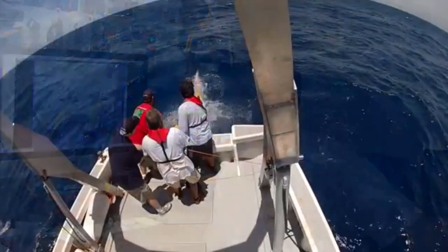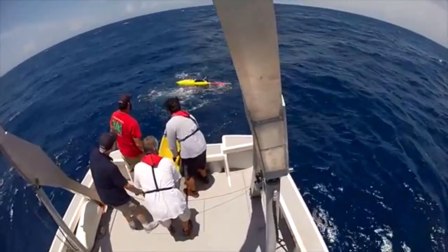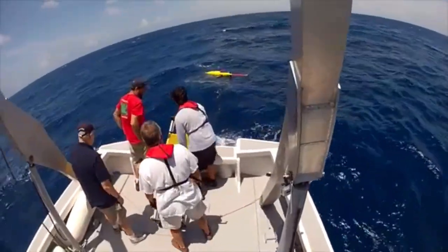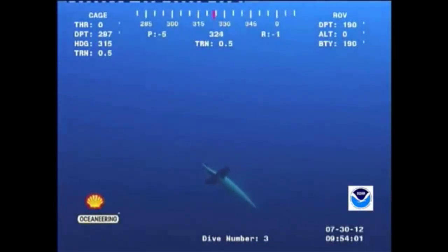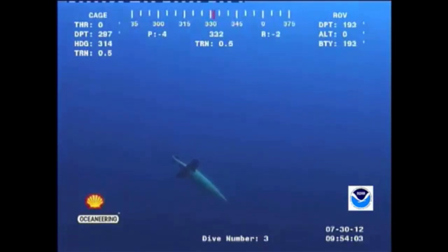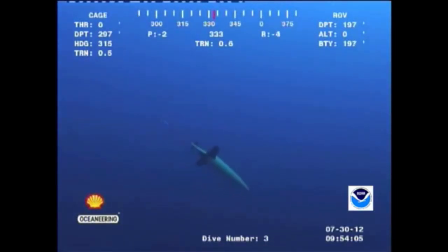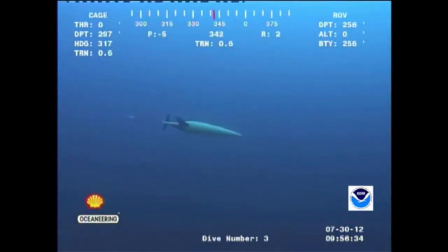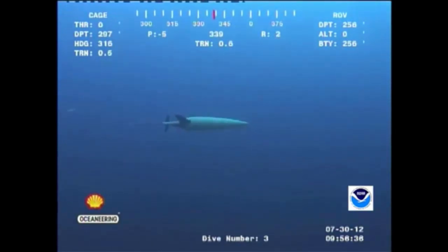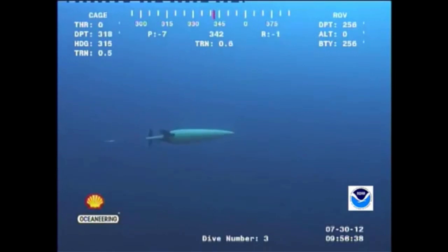The first aspect of AOML's underwater glider project involves going out to the study area and actually collecting data with the gliders. Once a glider is deployed from a surface ship, it uses small changes in buoyancy and its wings to achieve forward motion. Directional changes are achieved using the glider's internal adjustable ballast, rolling to the left or the right depending on the location of the next waypoint. Using these methods versus using a motor-driven propeller and movable wings allows the glider to operate for a much longer period of time than a standard AUV.